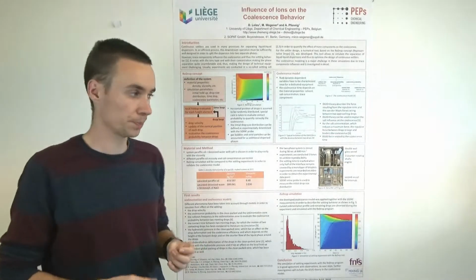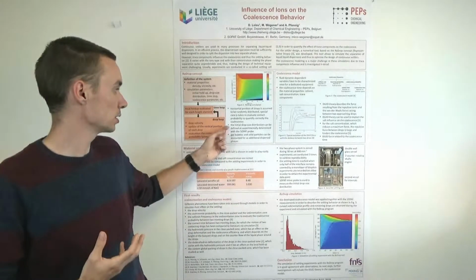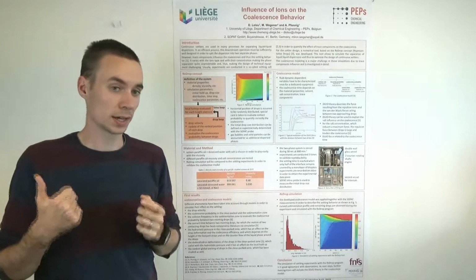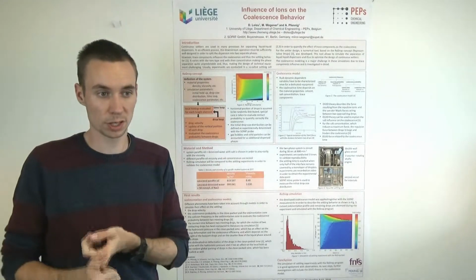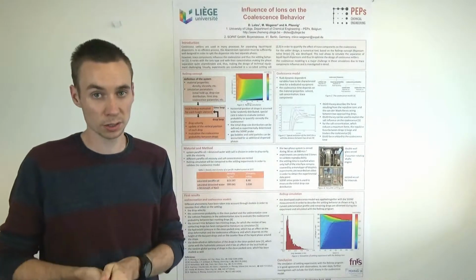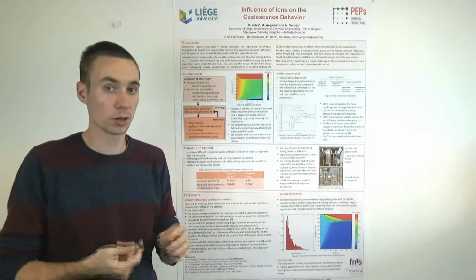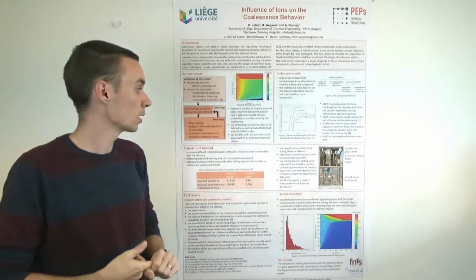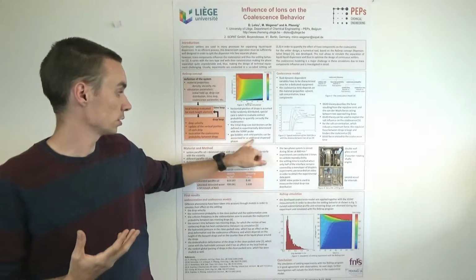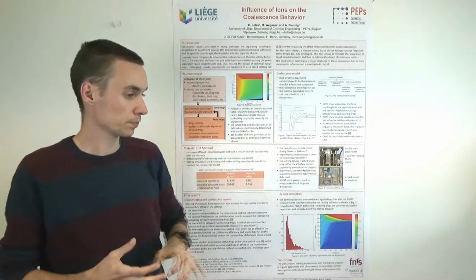Another point is the initial drop size distribution for the simulation. I can use the one that I measure experimentally with the SOPAT probe, or a theoretical one like the normal or log-normal distribution. And I can consider an additional dispersed phase such as gas bubbles or solid particles.